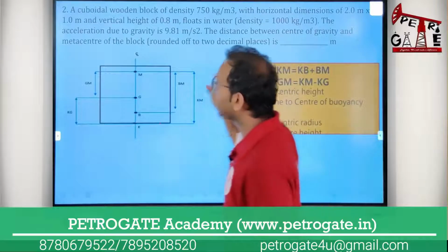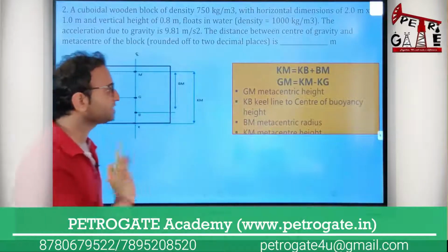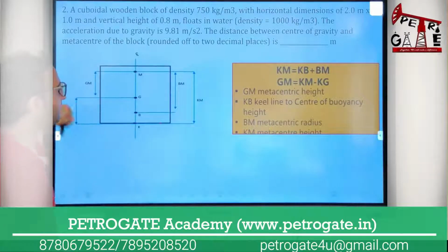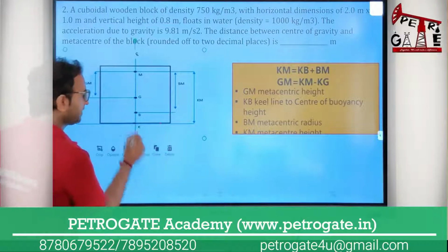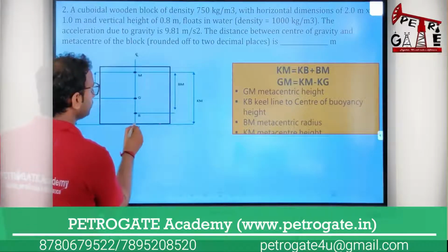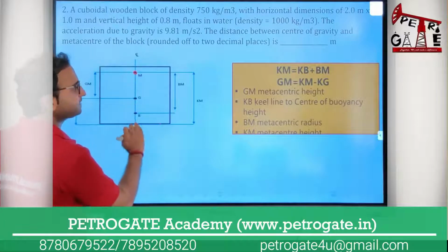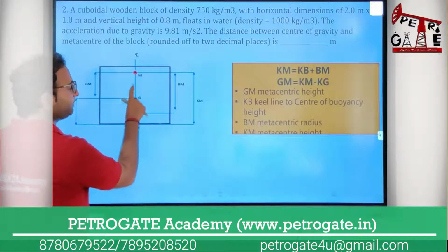Okay, so now how will I calculate your GM? Just tell me, can you tell me what KM means? KM means, I am telling you, this is your K and this is your M. KM means what? KB plus BM.